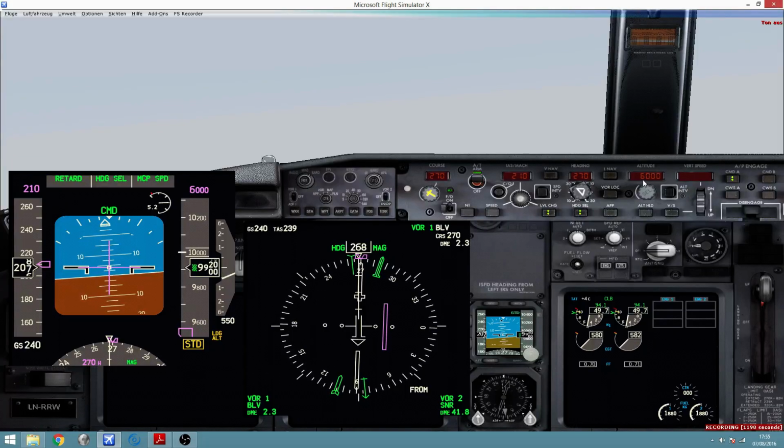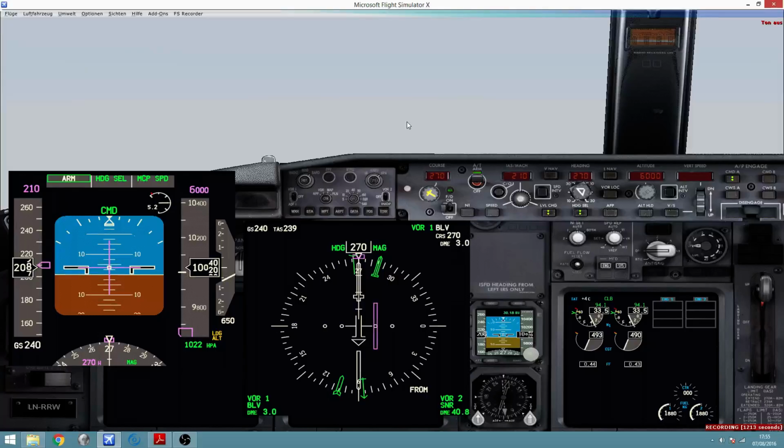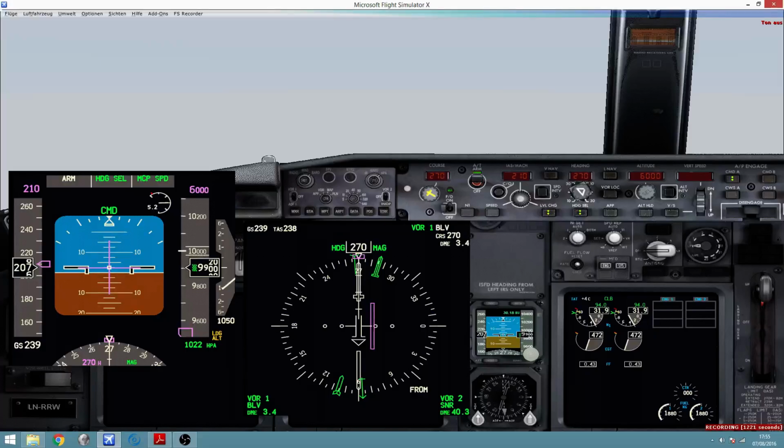If I am already going for an altitude, that means that I am going to penetrate the transition layer. I can already change from QNE to QNH, so I change from standard again to 1022. It's very important that you have the right vertical reference, otherwise you may end up against a mountain because of not complying with the proper vertical restrictions.